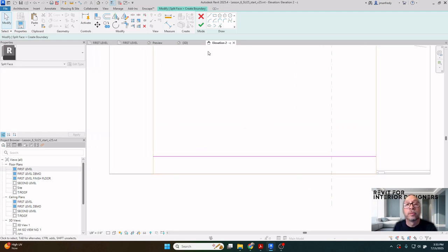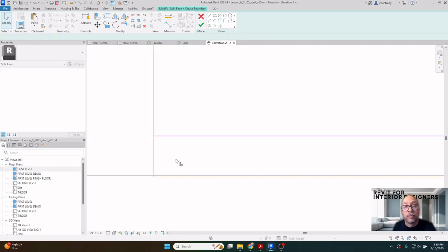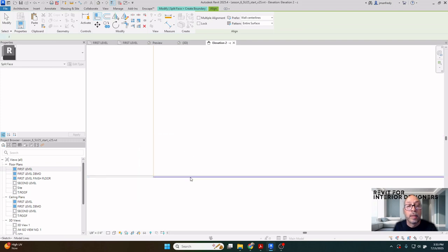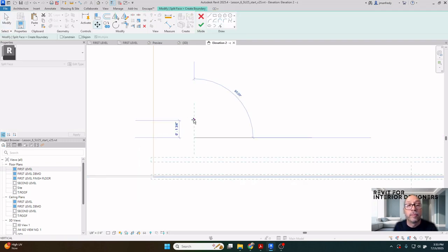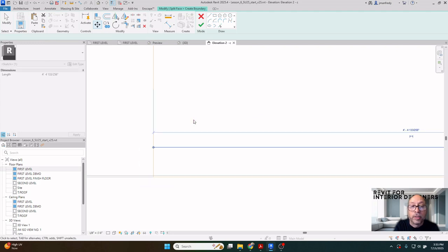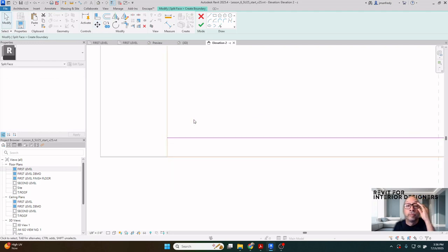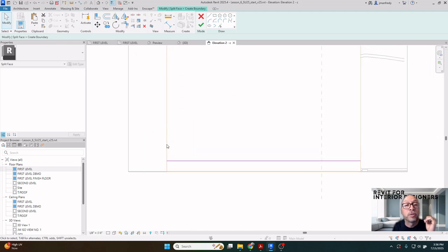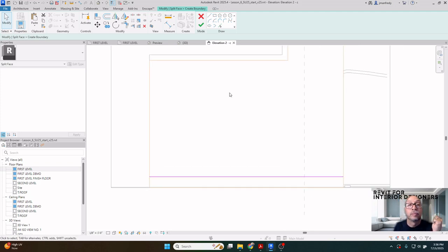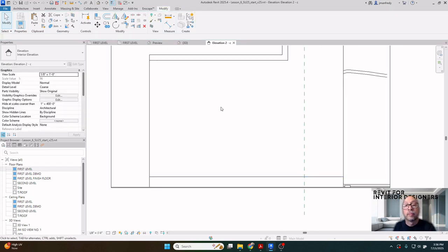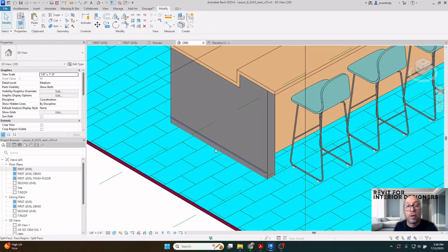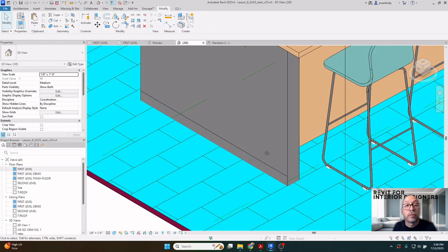So what I'll do is move it, align it with the floor, and select it again and move it straight up. Let's call it 3 inches. I cannot trace on top of the existing orange lines, but I can draw an independent line that touches them. That line allows me to hit OK, and that basically splits the wall into 2 separate areas.